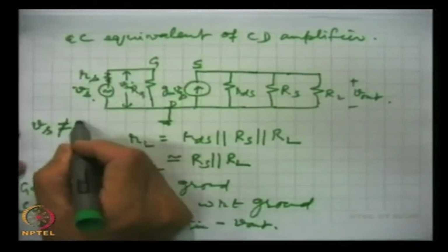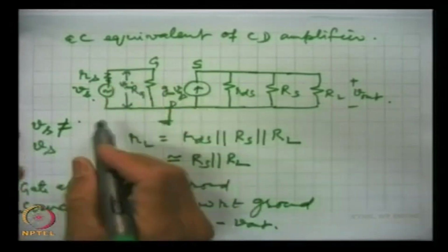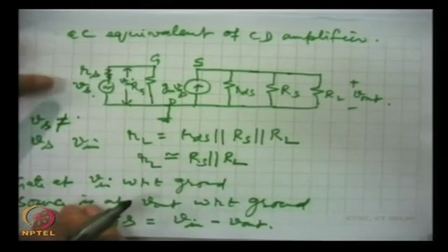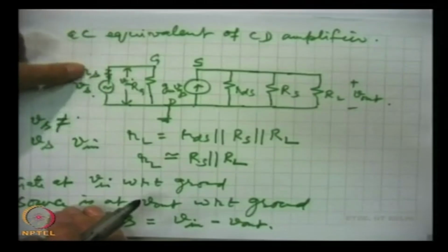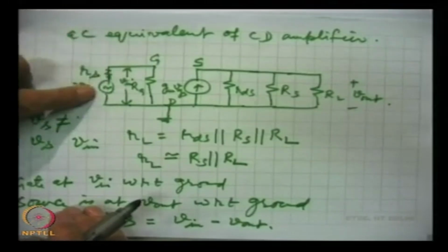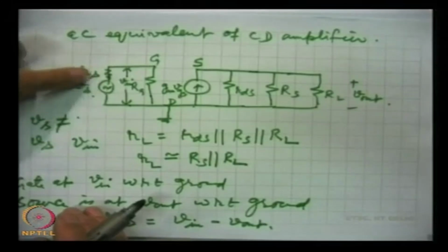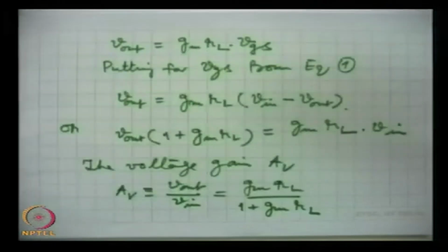So, this is taken as Vs, and here this is going to the circuit V in, because there may be some impedance which is normally associated with the AC source at the input, and there may be some drop across this. So, that is why the two have been taken as different. Anyway, so this is the expression for the voltage gain.